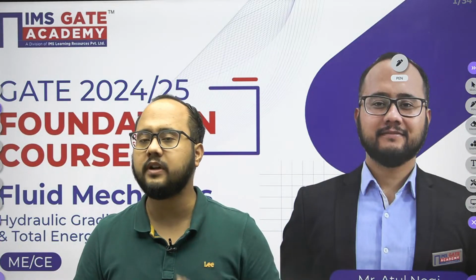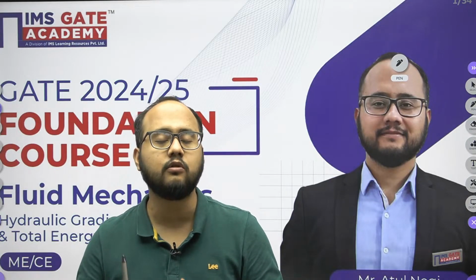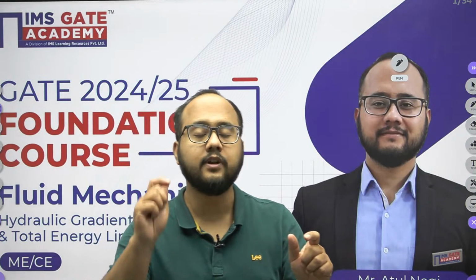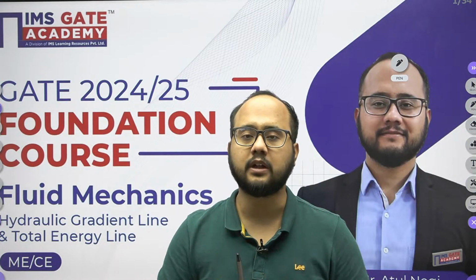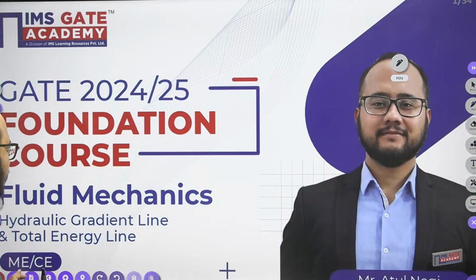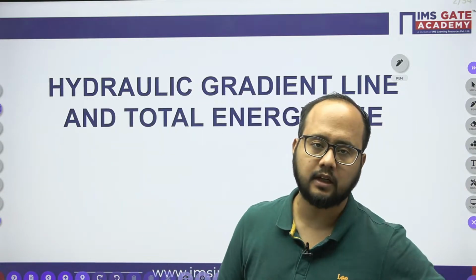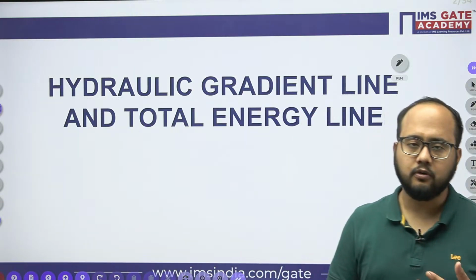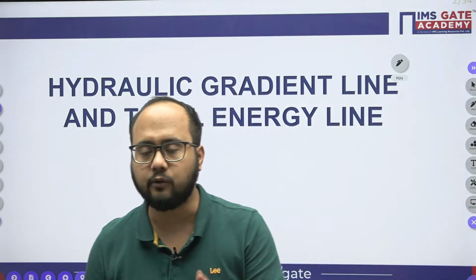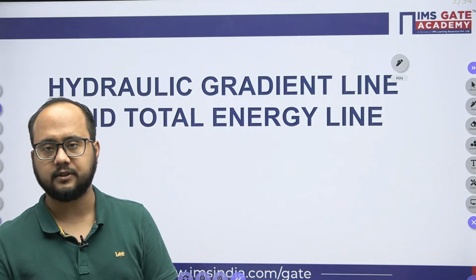Various cases we have discussed for the minor losses, and also how to calculate those losses. For major loss specifically, we discussed the Darcy-Weisbach equation, in which the formula is f L V square by 2 d g, and the most important part we need to understand is the friction factor calculation. Based on the type of fluid flow, the friction factor value will change. So we first need to calculate the value of friction factor, then only will we be able to calculate the head losses, right?